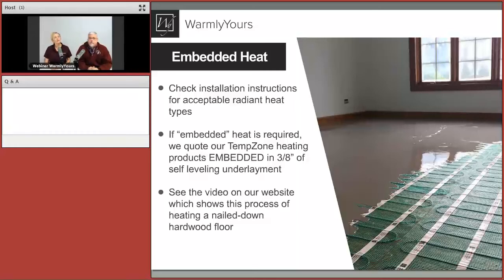What if you did a self-leveler, and then over that you installed your tile floor, let's assume a tile floor, and you're putting that then in a 1/4 inch of thin set? Oh, sure. If you're doing a tile install, that's what most people do, they'll put 1/8 or so just to cover the wire. Exactly. Then they'll come back and back butter the tile, put thin set down, and by the time you do that process, it ends up being right at around 3/8 of an inch. Right. So that's a great question, and I'm sorry that I missed that.